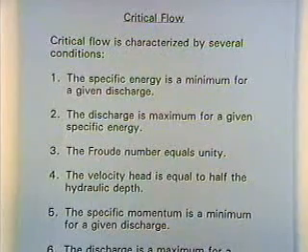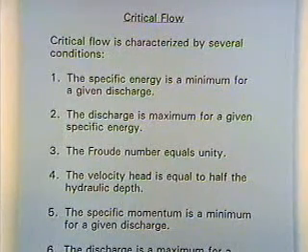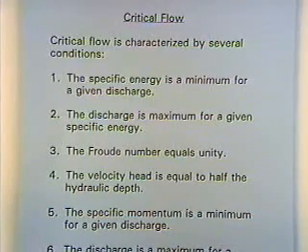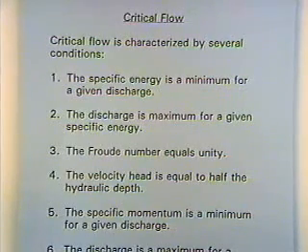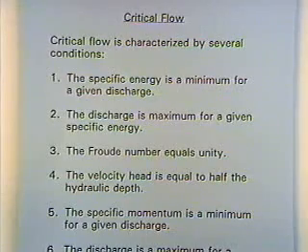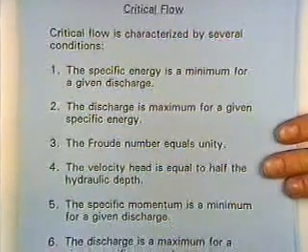Well, critical flow can be defined by, I've listed these as just characteristics or conditions that occur at critical flow. If you like, you could need a definition. Any of these conditions would serve as a formal definition of critical flow. Critical flow is the flow condition when the specific energy is a minimum for a given discharge, or the discharge is a maximum for a given specific energy, or the Froude number is equal to 1. And just a little sideline, the velocity head is equal to half the hydraulic depth.